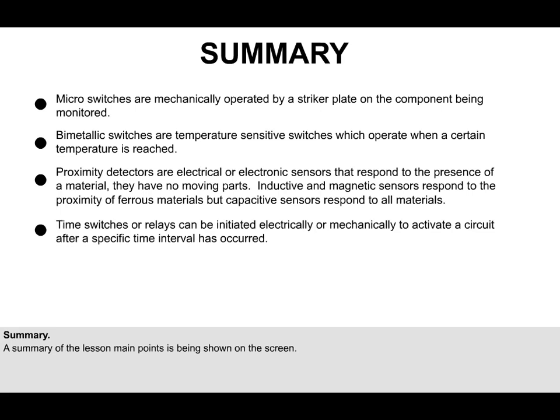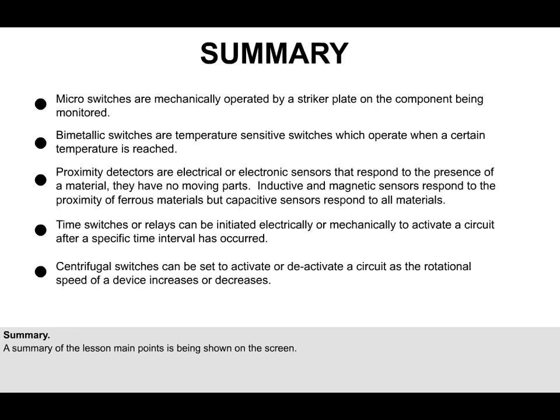Time switches or relays can be initiated electrically or mechanically to activate a circuit after a specific time interval has occurred. Centrifugal switches can be set to activate or deactivate a circuit as the rotational speed of a device increases or decreases.